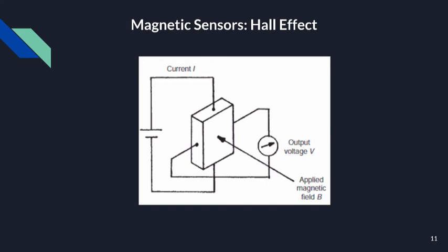The Hall effect is also commonly used in computer keyboard buttons, keys. When a key is pressed, a magnet attached underneath the button moves past a Hall effect sensor. This generates an induced voltage in the sensor, which is converted by a trigger circuit into a digital output. Such push button switches can operate at high frequencies without contact bounce.